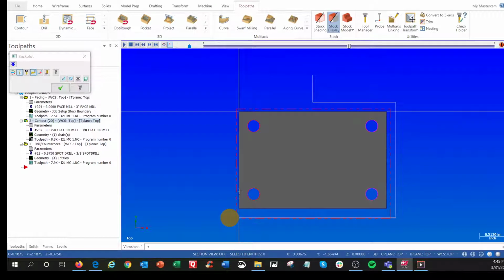Over here, this would be the X0, and this would be half the diameter of that. And then up this way, and then back to where we started right here. Then the exit move is when you shut off the cutter comp, which is a G40. G41 to turn it on. We're always staying to the left. We're always climb milling. Rarely would we use G42.